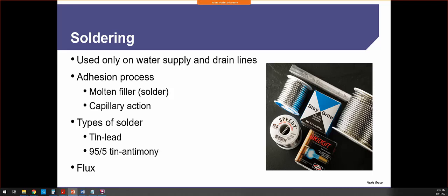If we start to apply heat to our copper for soldering, it's going to start to discolor, and we're not going to be able to bond two pieces. So what do we do? Well, we're going to apply a flux. It's a type of paste that goes to the inside and the outside of the fitting of what we're trying to solder. It's going to keep it nice and clean. So when we do apply heat to it, the solder will actually bond to the areas. All right.